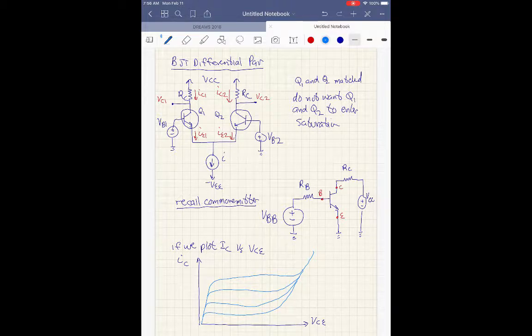And we can identify some voltages here. We can identify a voltage here, 0.7 volts. That number should be familiar for a silicon transistor. And I'm going to identify another voltage right here. I'm going to call that VCE max. Different books call these regions different things. Between 0 and 0.7 volts, or let's just say less than 0.7 volts, your book calls this the off region.